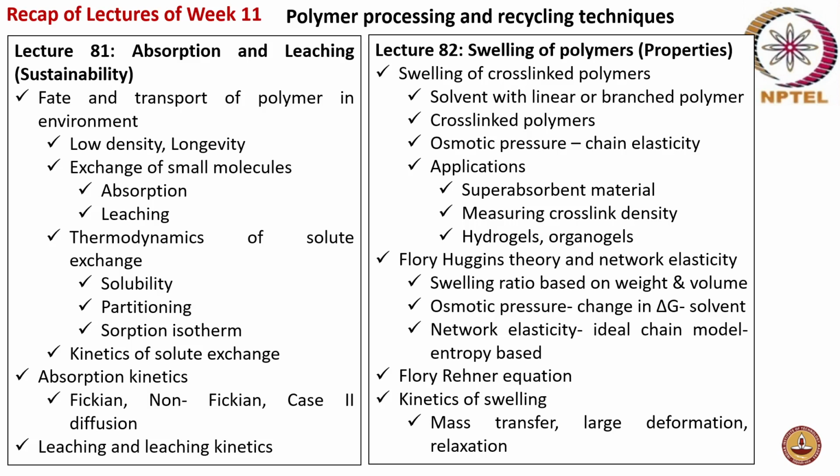And the equilibrium between the osmotic pressure and chain elasticity was discussed. The Flory-Rehner equation, and then applications of the swelling like in superabsorbent material, like in your diaper, and then how can you measure the cross-link density, and then what is the hydrogel, organogels, the Flory-Huggins theory and the network elasticity was discussed, the swelling ratio based on the weight and volume, the osmotic pressure, which is nothing but change in delta G, and then your network elasticity based on ideal chain model entropy based was discussed.